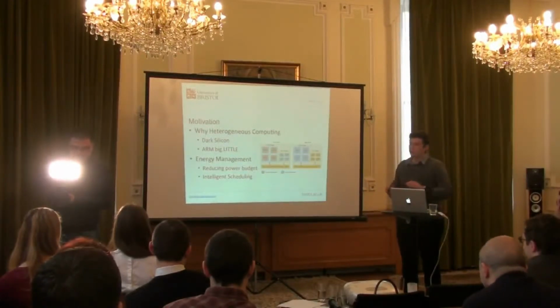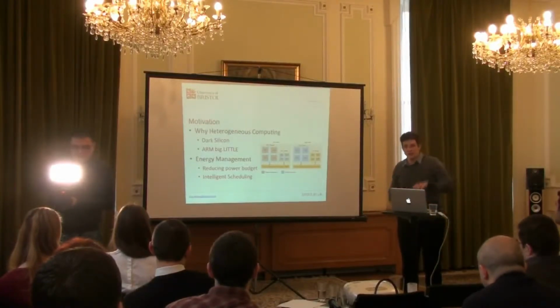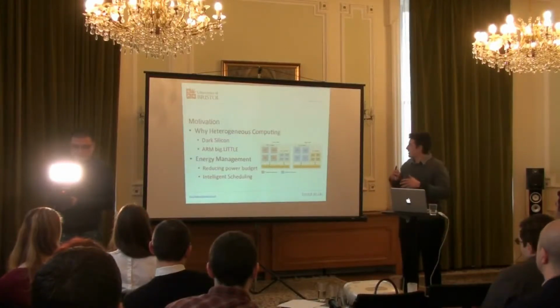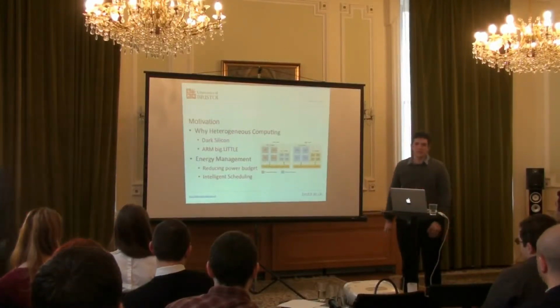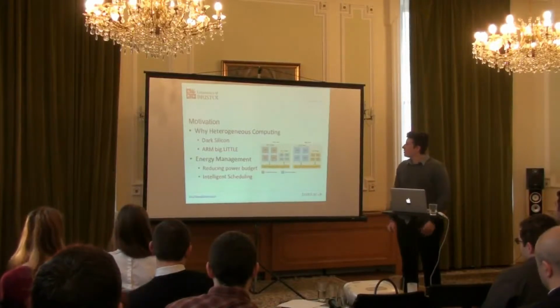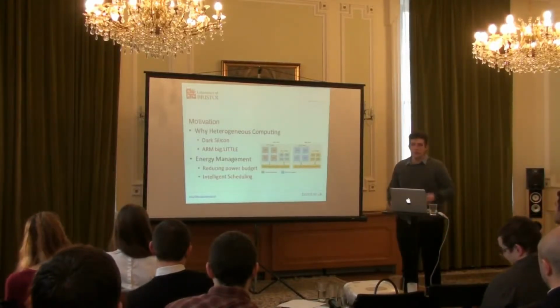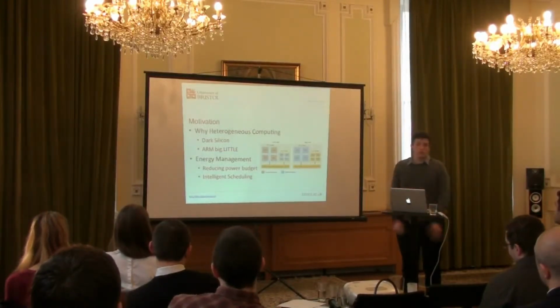Just having the ability to schedule tasks on a big or a small core, depending on whether they require more or less performance, is a big task on its own. The currently developed solution that's running on Linux, which is what Android runs on, which is what's running on most mobile devices that use ARM chips, just uses utilization thresholds, and there's not much further information about power.